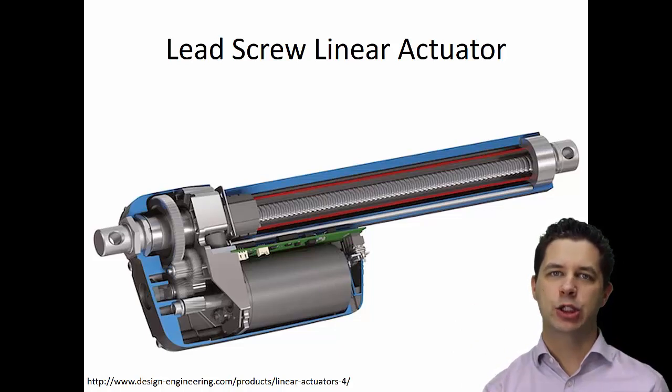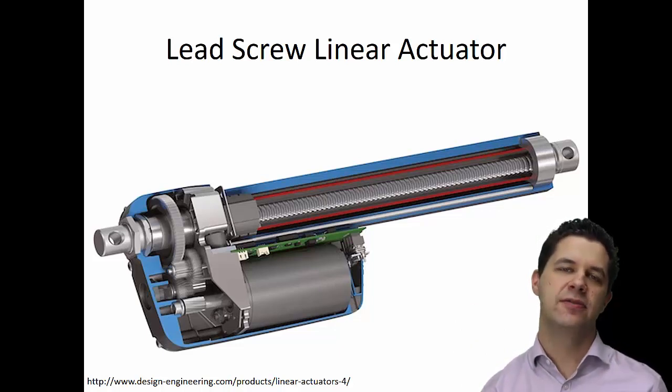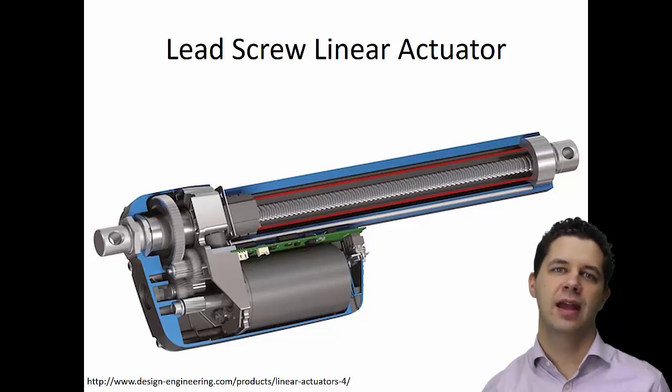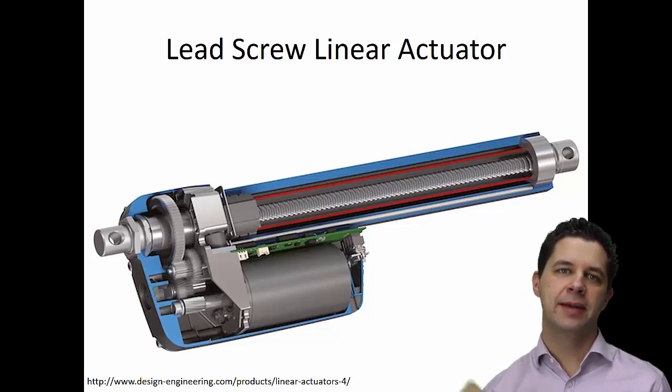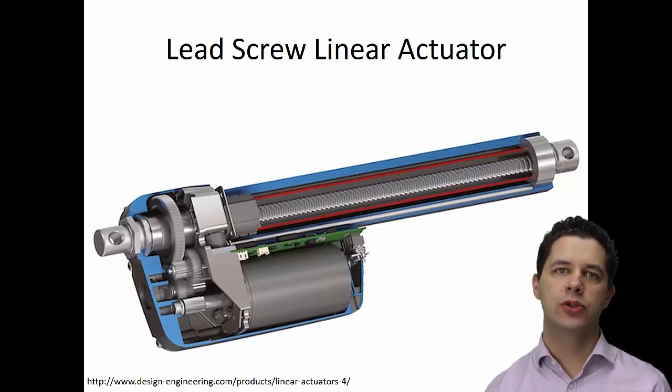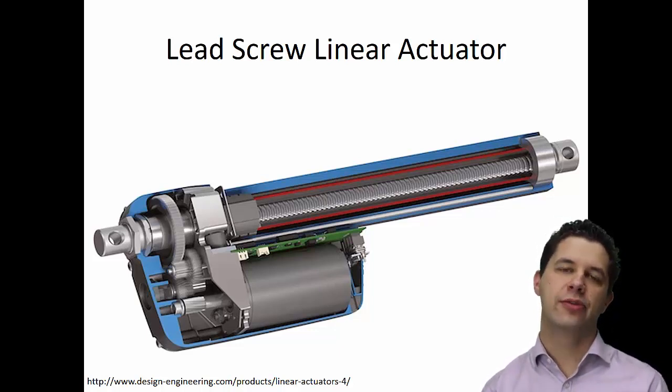And that's what we're actually turning a captive nut on to move our piston shaft in and out. We have a motor down the bottom there, and that motor is connected either via some gearing like we've got there, or a belt or a worm gear drive sort of system to allow us to control and turn that threaded rod.